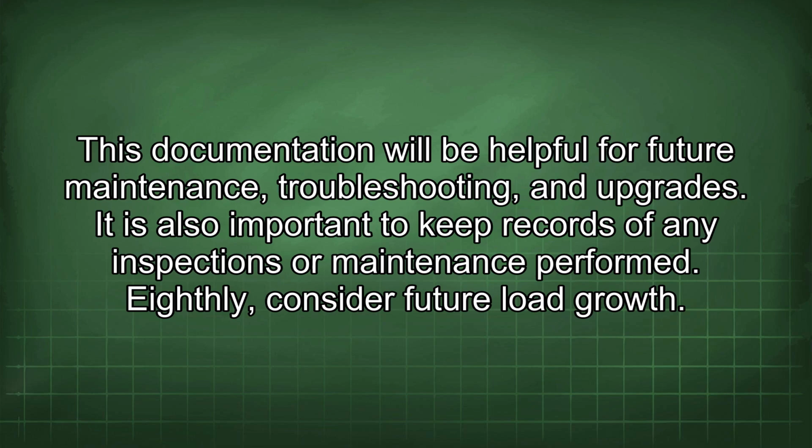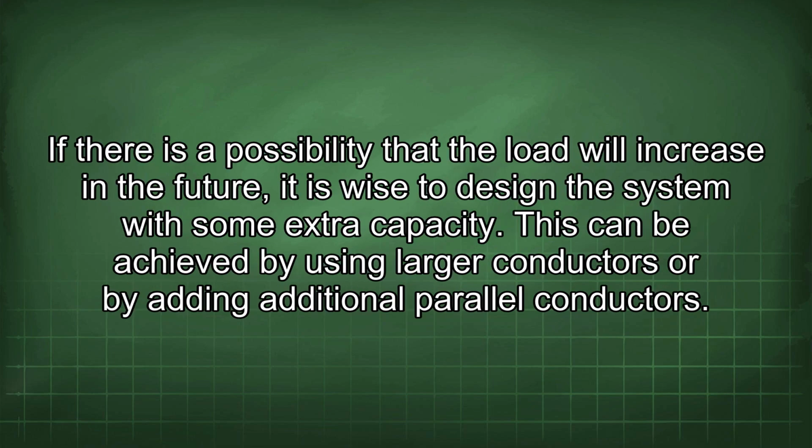Eighthly, consider future load growth. If there is a possibility that the load will increase in the future, it is wise to design a system with some extra capacity. This can be achieved by using larger conductors or by adding additional parallel conductors.